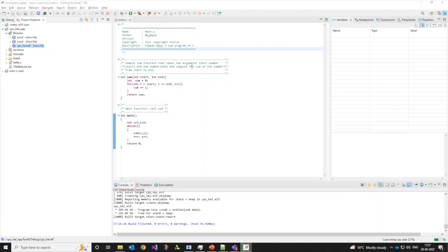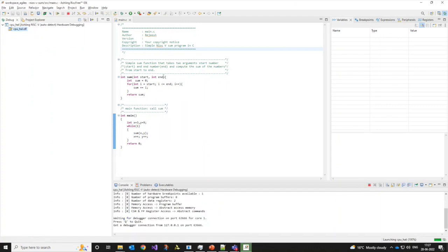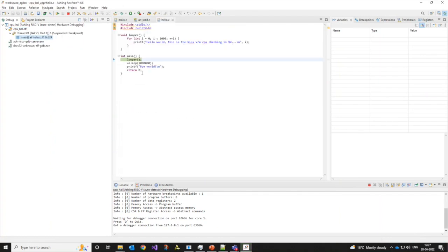So right now we should see again the program being downloaded and we run to main of this HAL based application, which we built right now. So here you can see we have run to main, and what this application does is actually use the HAL. You can see when we use this printf here, with the help of HAL, it is actually printing this to the UART.